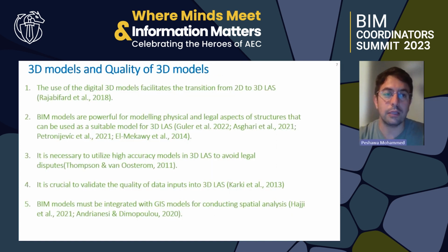So the use of digital 3D model facilitates transition from 2D to 3D LAS. And BIM models are powerful for modeling physical and legal aspects of structures, and are a suitable candidate to be used for 3D LAS. However, it is very important to note that BIM models must be of very high quality to be used in a 3D LAS in order to avoid legal disputes in the future. That's why it's crucial to validate the quality of BIM models before using it into 3D LAS.